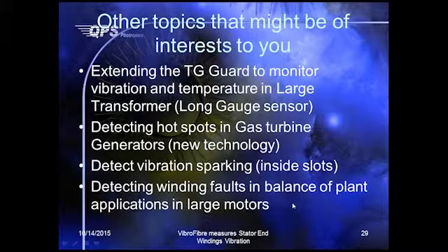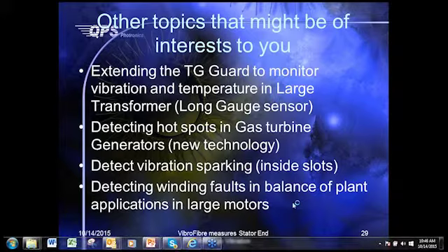Another potential area that we want to go into is balance of plant applications. Let's say you have a large motor running cooling water in your power plant, and the traditional condition monitoring solution is to place a piezoelectric vibration sensor, an accelerometer, on the bearing housing.